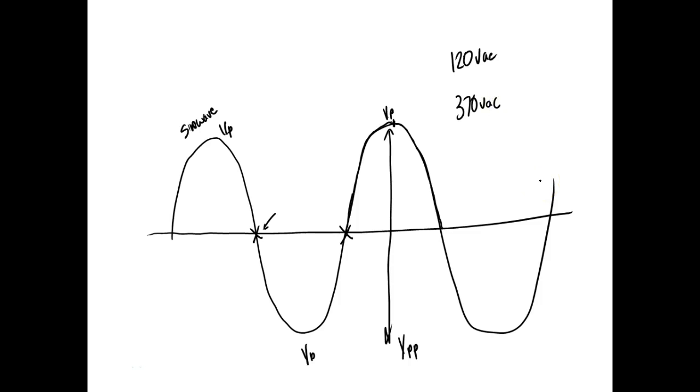An oscilloscope would show you that because the oscilloscope shows you what's there. Your meter's going to do what? Your meter averages everything out. So if I was looking at a pulse waveform, the voltage would vary depending on the width of these pulses right here. And we'll look at that too later on. But my scope would show me the pulses. My meter would do what? Average it out. So that's the advantage of an oscilloscope over a meter. It actually shows you what's there. A meter can't see noise riding on top of your DC power supply. A scope could.